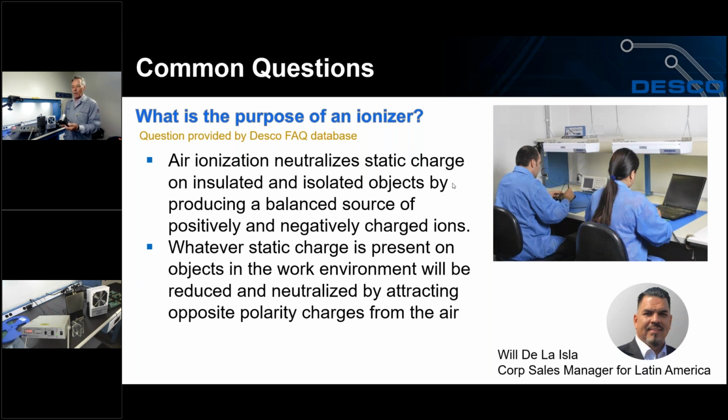Yes, thanks, Will. Inside the survey kit, there's what's called an ionization test kit. Basically it takes the static field meter and has this hood, which is isolated from the case of the field meter by these standoffs. So now I have an isolated conductor by which I can collect the ions that I'm going to put on the conductor, and that's with this little static generator or voltage generator that we have. This is one test method or piece of test equipment I can use. You can also use a charge plate analyzer, which I described. So I'm going to put a charge on here.